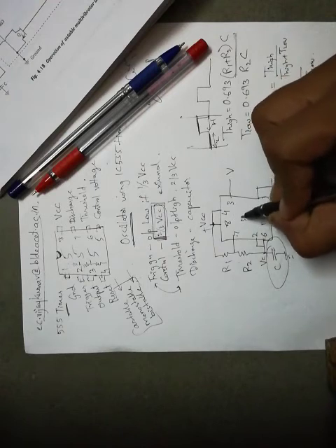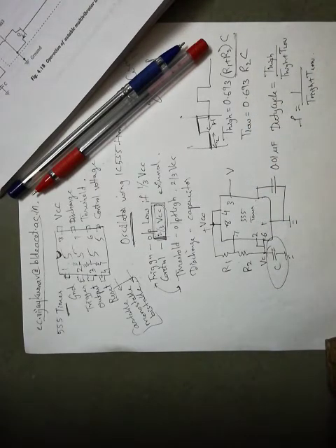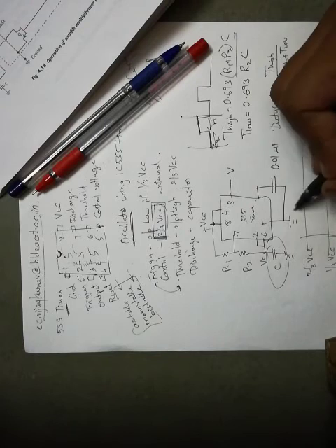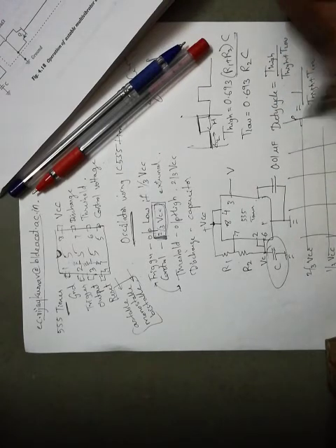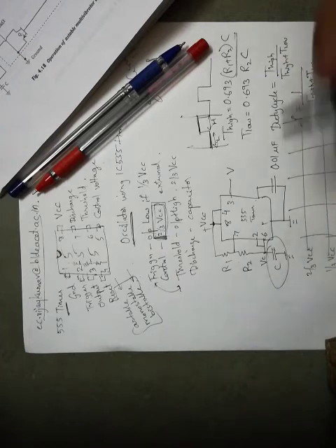So this is how we'll use 555 timer to design an oscillator. A careful observation of how this is going to happen. We'll observe the voltages on the capacitor when it reaches 2/3 VCC and when it reaches 1/3 VCC. We'll take a few lengths of signal.